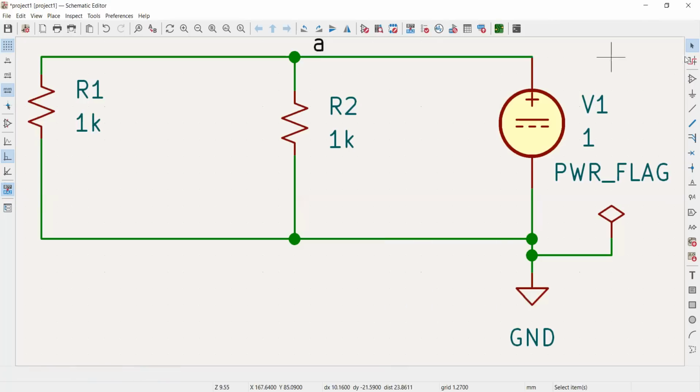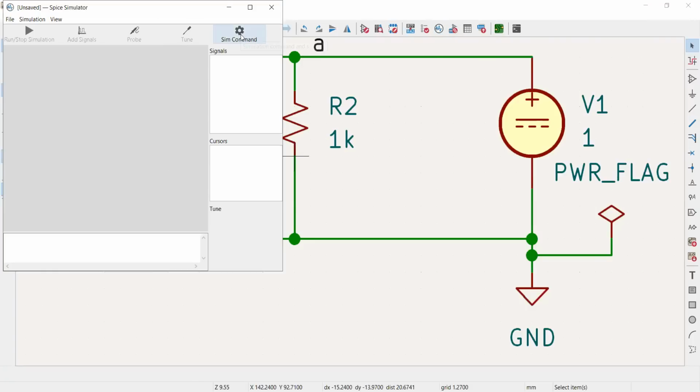How to do that? So look at this option, highlight wires and pins of a net. I select this and I click here, and that's the whole net A there. On the net A, I have this voltage. And here, of course, it is the ground. So let's run this simulate circuit in Spice. Then I will choose the simulation command.